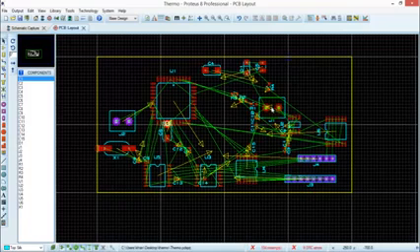So the next thing is you need to auto route all the signals. Select this option, auto router. So what will this software do? It will automatically connect all the components with the trace size which you have mentioned in the design rule.